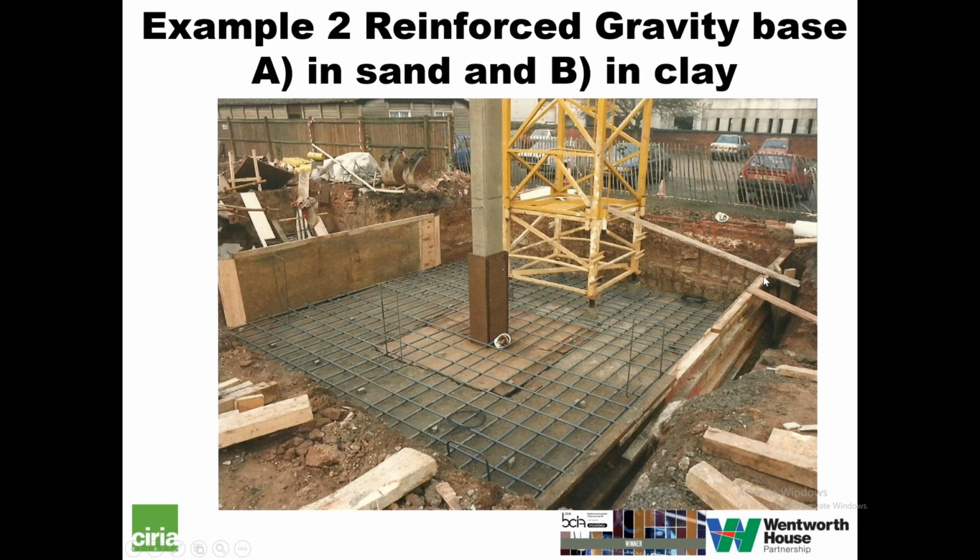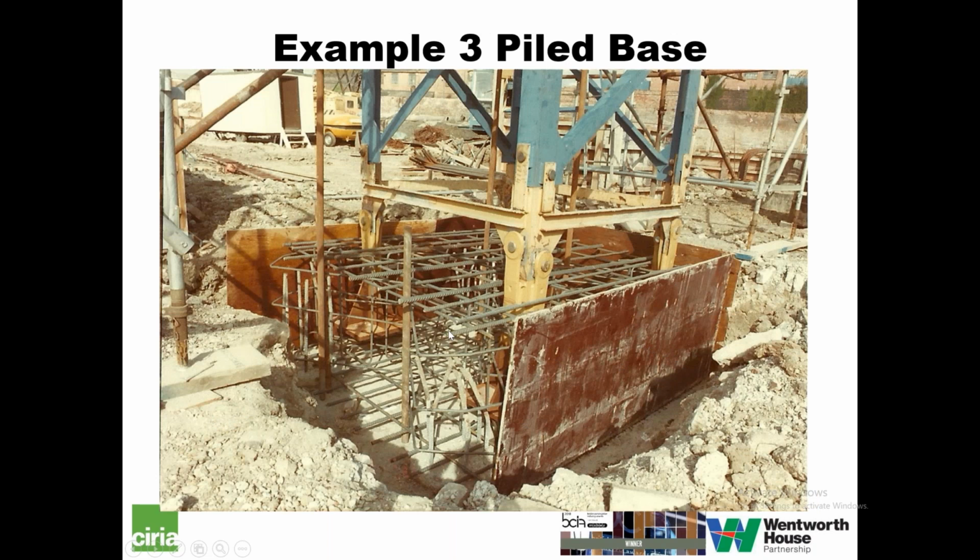Here's a reinforced gravity base in sand and or clay. This one, as you can see, was combined with a column foundation. Not an unusual situation in a busy city centre site. This is a pile base. You note the legs here are clear of the piles, which is a key thing to remember if you're designing a piled base. Otherwise, you'll find these plates get in the way of the pile reinforcement. And the pile reinforcement needs to have a full tension anchorage into the base because they're tension piles as well as compression piles.